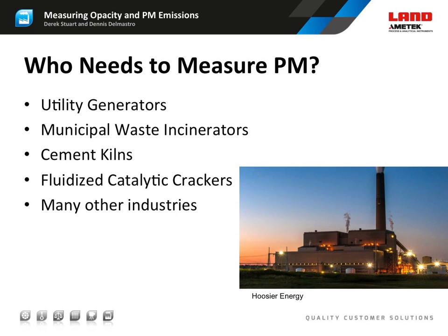Hello, I'm Derek Stuart, Industry Product Manager for Power at AMETEK Land. I'm going to talk about measurements of particulate matter, or PM. As Dennis explained, opacity measurements give a measure of the amount of dust and smoke leaving the stack from a combustion process. A PM monitor quantifies those emissions in mass units, usually milligrams per cubic meter, but sometimes grains per dry standard cubic foot.